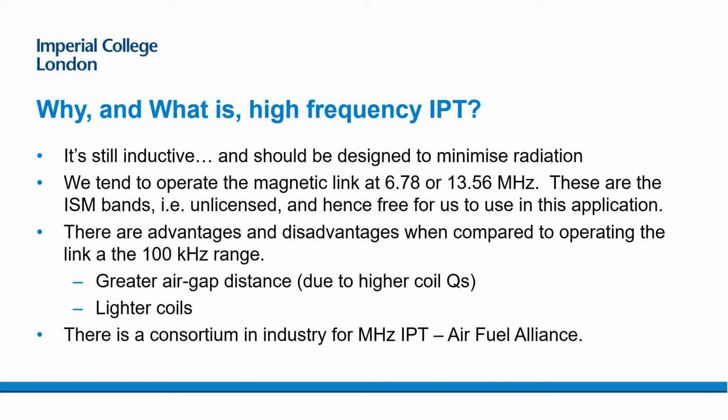So clearly, high frequency, well, the stuff that you've heard at the moment, primarily focused on electric vehicle charging, is operating at around 100 kilohertz. The Qi standard operates at around 100 kilohertz. And what I'm talking about here are systems that operate typically at 6.78 or 13.56 megahertz.